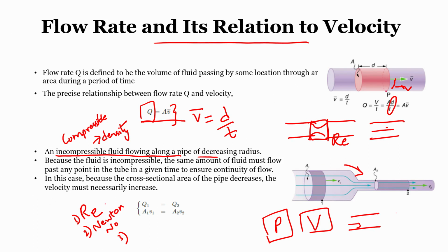So, you can get into the details about Newtonian, non-Newtonian fluids, compressible and incompressible fluids, and these parameters will be helpful when you have to simulate this in a virtual environment, and you have to put in something called boundary conditions. When you have boundary conditions, you should give the platform inputs such as the inlet pressure, outlet pressure, the type of tissue property, and the type of fluid, is it compressible or not, what would be the density of the fluid. All of that comes when you have to do a CFD simulation.